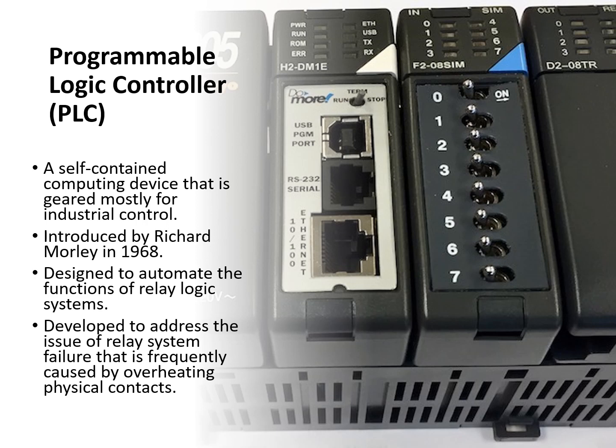It is programmed to realize the various functions required by industrial processes such as robot controls, equipment operations, status diagnostics, and so on. The PLC instruction set may include logic, timing, counting, communication, math, and I/O, input-output control. An Ethernet-enabled PLC is shown in the figure.